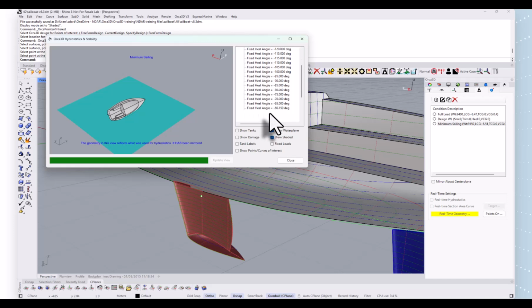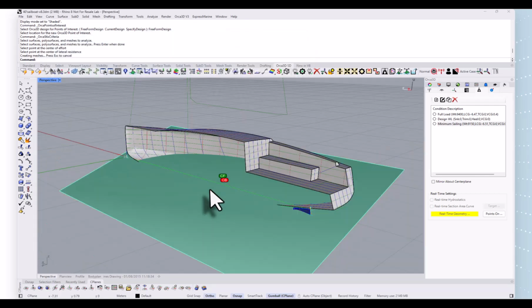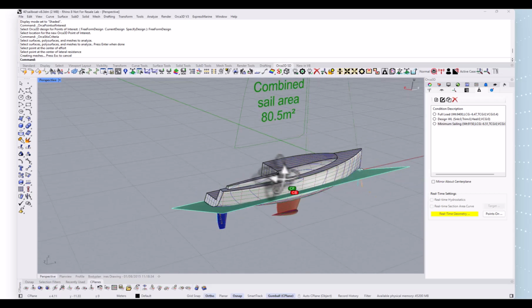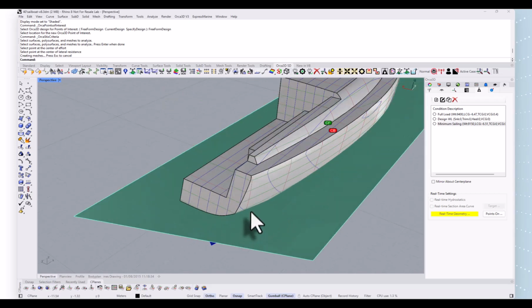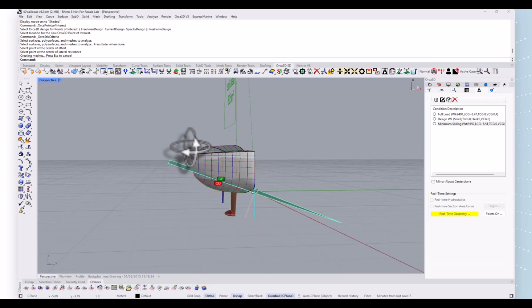Before reviewing the report, notice that one can isolate a particular step of the rollover and insert the corresponding floating plane into the Rhino graphical space. This may allow, for example, to check some measurements, such as freeboard heights.